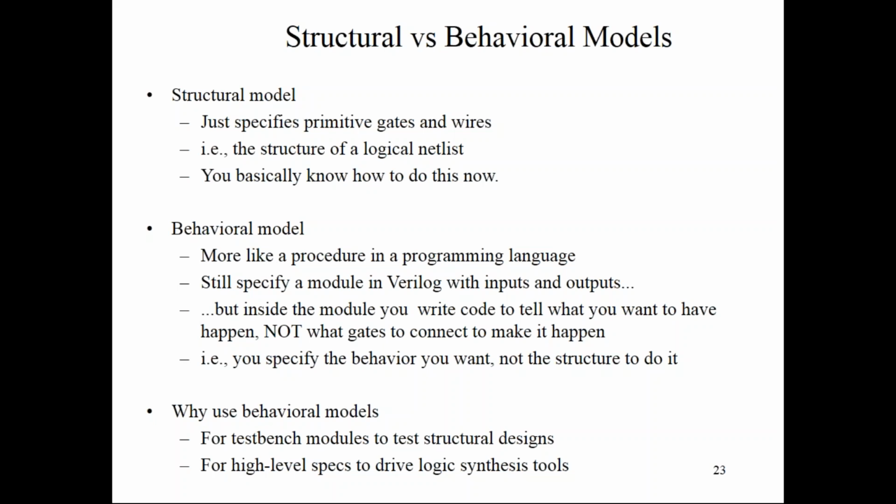So that information is described in structural modeling. But in the case of the behavioral model, if the selection line is 0, then output D is equal to A. Else if 1, then D is equal to B. Likewise, I am describing the model based on an if statement or case statement, describing the procedure or algorithm. That is the difference between structural and behavioral models.